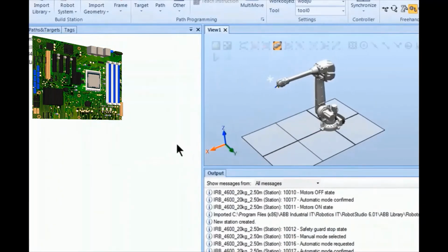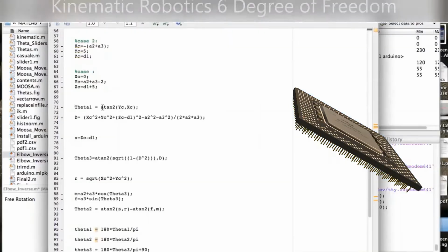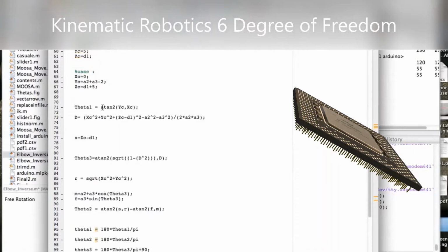Afterwards, getting the gripper position and orientation by using the forward kinematics solutions. And finally, computing the Euclidean distance between the initial position and orientation and the final position and orientation to get the error of the two solutions.